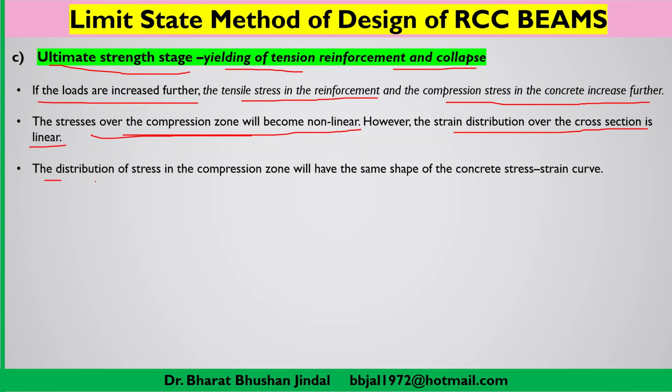The distribution of stresses in the compression zone will have the same shape as the stress strain curve in the case of concrete. So stresses will be distributed, and the shape of the stresses in the compression zone will be just similar to the shape of the stress strain curve of concrete.